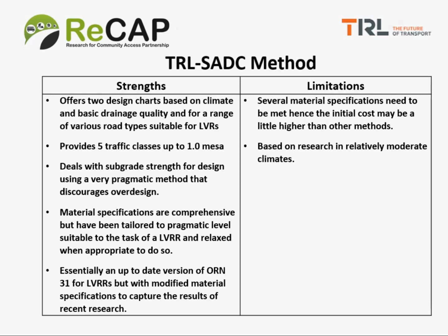Subgrade strength is measured in the soaked state, but that doesn't mean that we're expecting the subgrade to be soaked in reality. We're just labeling or indexing the subgrades that are available. So basically, in the experiments on which the method is based, the subgrades were soaked, and if your subgrade is soaked and has the same value, then it will behave in the same way that the experimental pavements behaved. And of course, those in the design chart are the ones that behave well. So there should be no worry about subgrade strength.